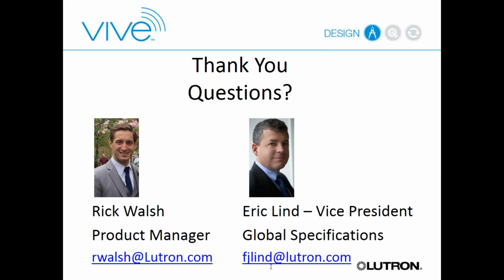A couple questions about shades. Some folks that are familiar with Lutron obviously know that we have a very broad offering of wireless shades that can control in an automated fashion the amount of daylight coming into the space. The Vive system, the Vive wireless hub, does not talk directly to those shades, but it does allow you to have shades in the same space. As an example, you could have a single Pico controlling both the lights and the shades in that space with a scene, or you could have two Picos in the same faceplate, one controlling the shades and one controlling the lights, to give those people the ability to improve their comfort by adjusting those shades. That's absolutely something you can do with that system.